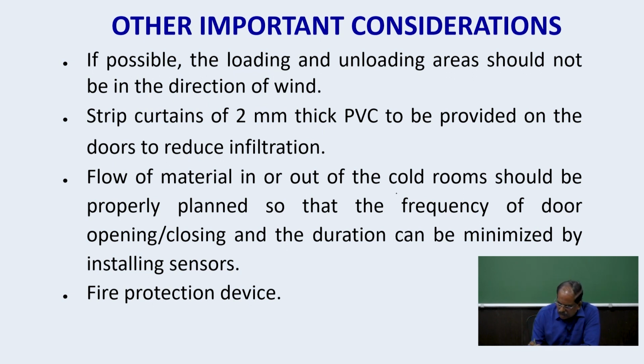Flow of material in and out of the cold room should be properly planned so that the frequency of door opening is minimal. This is very important. The opening and closing of the door should be as minimal as possible. Otherwise, it will add up to the heat load. And the duration can be minimized by installing sensors.